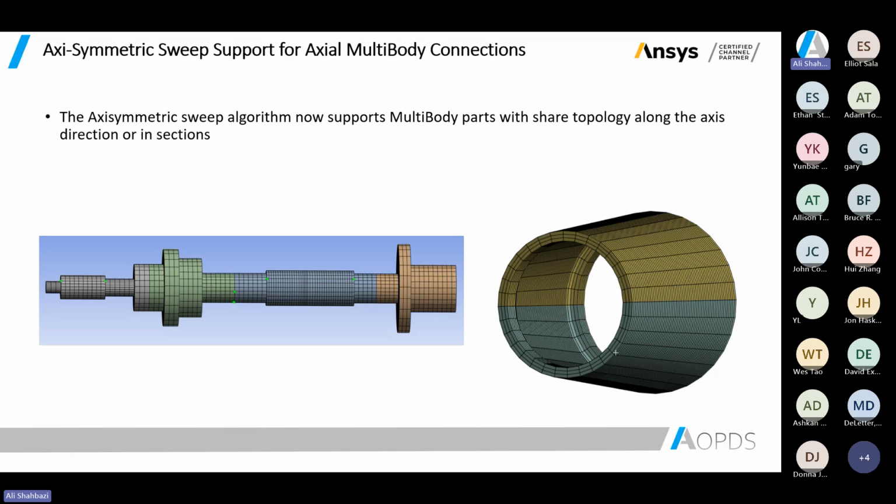One way is to define a specific contact between them, right? Mesh them separately, define a specific contact, like a bonded contact, and assume that they are connected, and move forward. A more accurate representation, in my opinion, is defining conformal nodes and defining matching nodes between different components. They may even have different material properties. It doesn't matter. This is meshing, and it goes. It cares about the nodes and the physics and stuff like that to solve them.